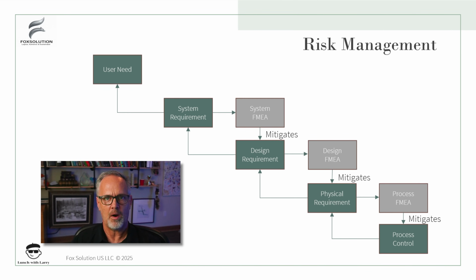So if we have a design requirement that is maybe something like, in a sterile barrier bag, the sterile barrier won't migrate harmful bacteria. Some of the physical requirements might be that you want to use Tyvek, or you might have a 3/8 inch bag seal. And those are critical dimensions and/or characteristics of the design that are necessary to assure that that bag doesn't migrate the harmful bacteria. So in the design FMEA, we're going through from a mechanical design standpoint now, because we know what component that requirement is deployed in. I can go through from a design standpoint and define everything that's required to be in the design to give me that migration remediation.